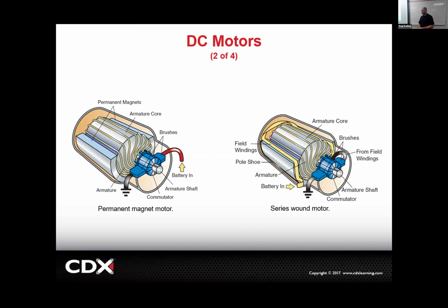Her dad calls, hey, the Jeep won't start. Can you diagnose it? Yeah, sure. Go over after work, roll under there. Just say, hey, all I need you to do is hold it in the crank position. Boom, I measure at the starter. When he holds it to crank, I get 12 volts right here. That's it. That's all I need to know.